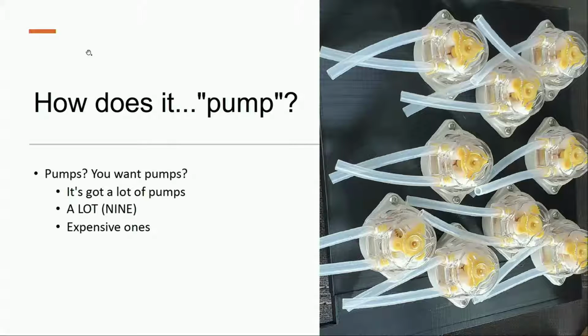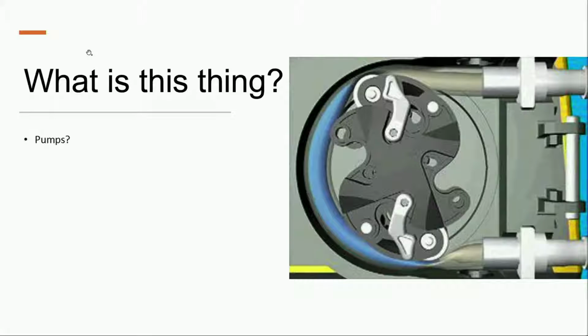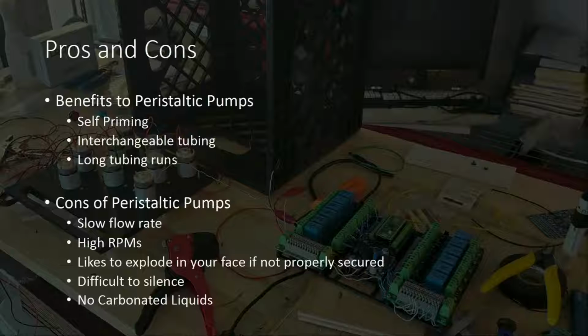If you don't know what peristaltics is, there's different kinds of pumping systems out there that our team researched to figure out what would be the best way to move the liquids around. Because we want this to be sanitary, we want something we can clean. So we went through different types of pumps, and the peristaltic pump actually turned out to be the perfect solution. So as you can see there, the gears actually rotate and push the liquid through the tube without ever actually touching the liquid. So some of the pros, it's self-priming.